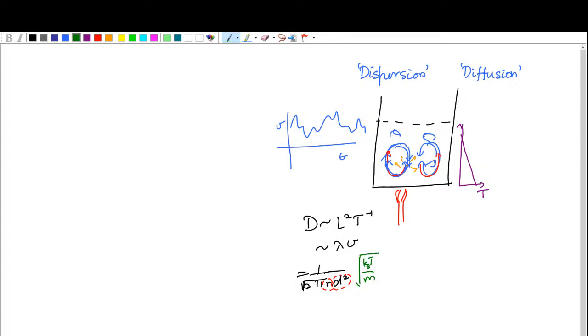And we had estimated both of these in class. This worked out to be about 300 to 1000 meters per second. This worked out to be about 0.1 microns, which is about 10 power minus 7 meters. And on this basis, for gases, if you multiply these two, the mean free path times the molecular velocity, you get something that is roughly 10 power minus 5 meters square per second as a typical diffusivity in a gas.